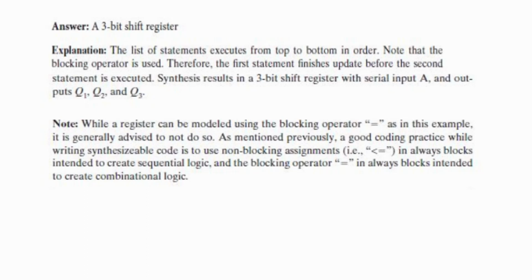If you want to understand non-blocking and blocking operators in more detail, they are often used in these always blocks, and these non-blocking and blocking assignment operators are used to create combinational and sequential circuits. So we use the non-blocking assignment operator, the less than or equal to, to create sequential circuits, and the equal to blocking operator to create combinational circuits.